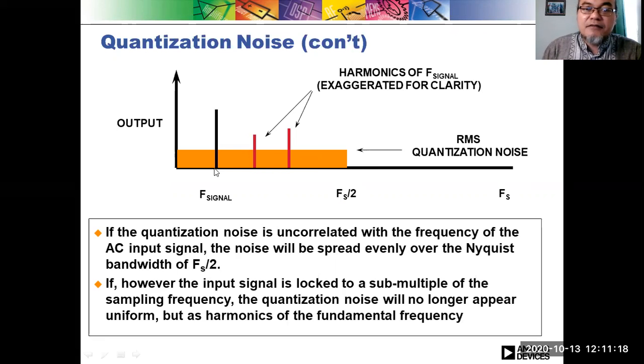the maximum bandwidth of the signal, right? Based on the Nyquist-Shannon criteria, we have to sample this signal at least at fs over 2. But usually it would be better if we sample it with an even higher sampling frequency. So this is the harmonics of the frequency of the signal. One multiplied, this is 2 f signal, this is 3 f signal.